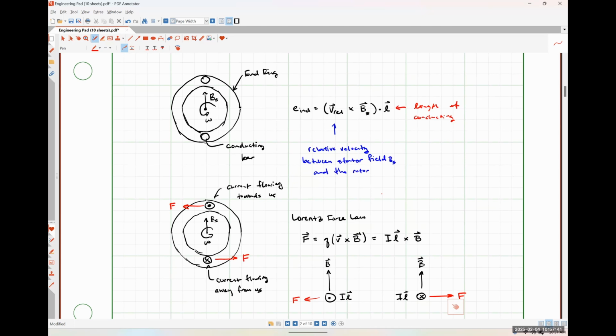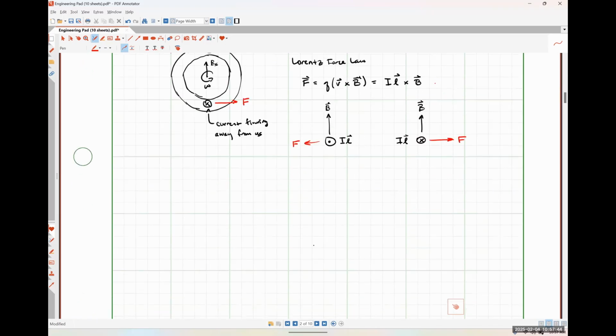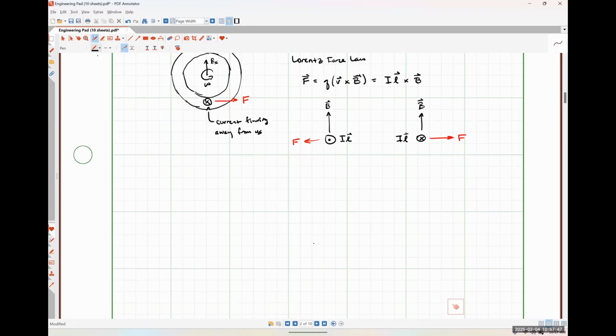So let's see here. Our stator field speed, NS, this is the relationship from the slideshow, is going to be 120 times Fs, where this is the frequency of excitation of the stator windings, divided by P, which is our number of poles, right? So this is effectively the absolute maximum that could ever happen.